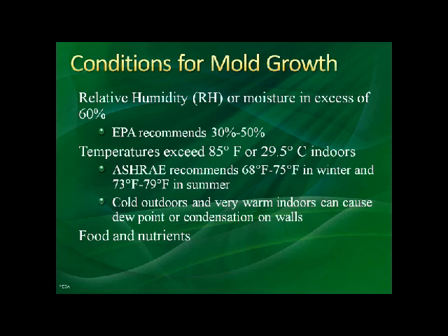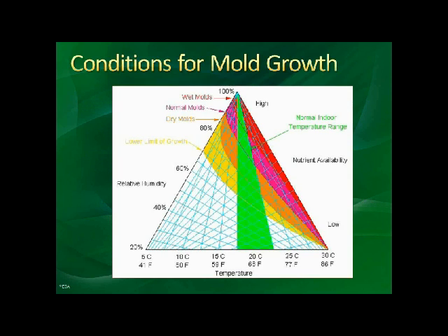Dr. Kolowski of Penn State University designed this slide many years ago for us. This gives you a generic psychrometric chart that shows how mold grows and when it'll start to grow. As you can see, it'll start to grow really significantly at 60% and higher.